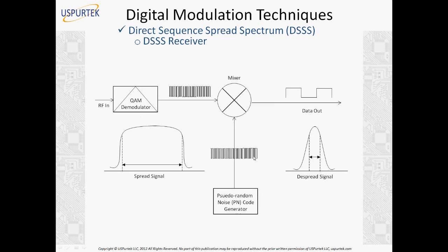Okay, there is a question here. How does it increase bandwidth by just multiplying with PN? Okay, let's go into a little more detail. If you take a Fourier transform of a low bit rate data signal, in the output you will see low frequency components. But if it is a high bit rate data signal, that is actually a combination of high frequency components. High frequency components mean more bandwidth. You have more frequency components, ranging from low frequencies to all the higher frequencies.